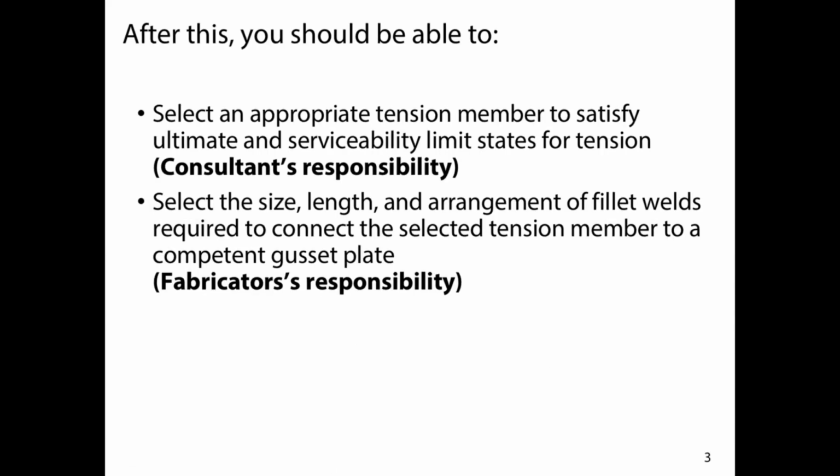The outcomes are basically the same. I mean, the first one is if you're specifying welded connections, you should be able to select an appropriate tension member to satisfy the same serviceability and ultimate limit states we talked about before. It's really not going to be that different from what we did for bolted connections. It's just now we have a welded connection and we need to change how we consider the effects of having a welded connection on the shear lag and net section calculations.